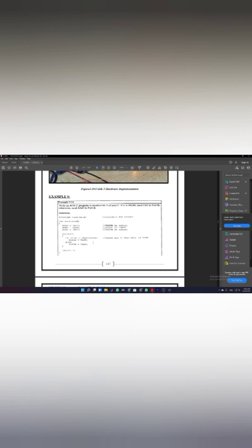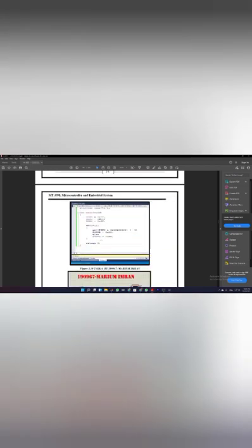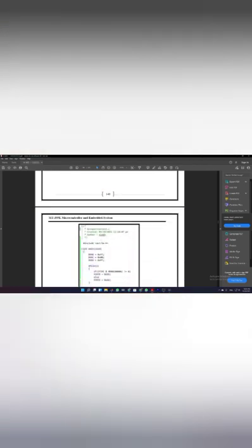Here the while loop is executing; while 1 means that it will run forever. If the pin C AND operation is being performed, it checks the 5th bit. If it is high, then 55 will be printed, and if it is low, then AA will be printed.